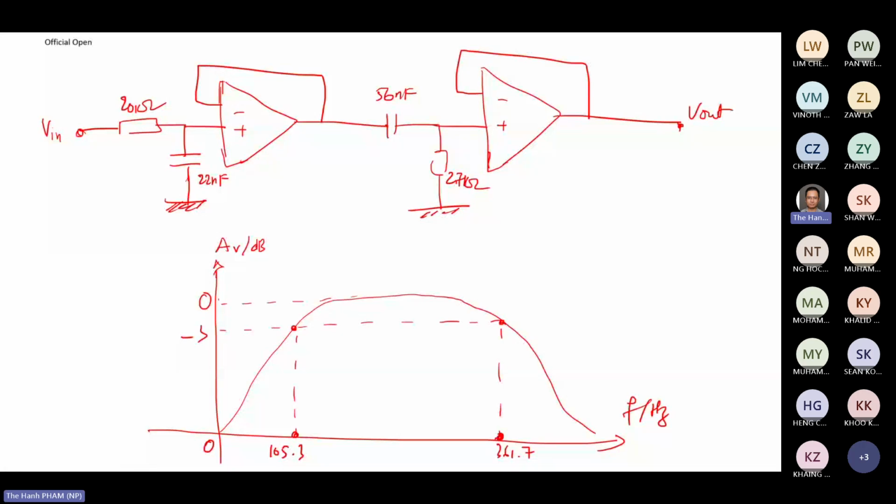It doesn't matter because imagine if this one is low pass first, then you go to high pass. Suppose at this point you have all frequencies, then because of the low pass filter, the cutoff frequency is 361, right? So you still have up to about 300, for example. Then the high pass will remove everything below 105. So at the end, you have 105 and 361.